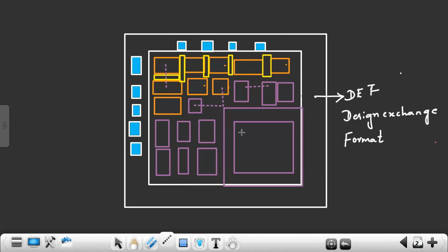After going to physical design, we cannot do logical restructuring. Logical restructuring means changing of cells, which I cannot do. I can only fix the violations by VT swapping, by upsizing the cells, or by increasing or decreasing the skew. These methods I can do, but logical restructuring can be done only by the synthesis tool.